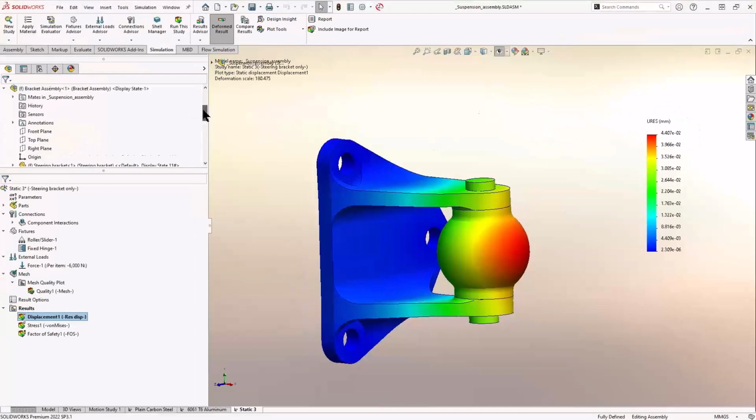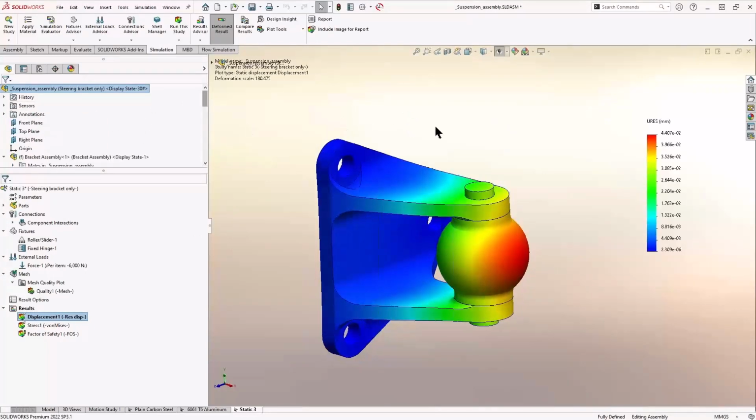Well, that survives the deflection goal, and I can tell because my sensors are not red or yellow. I didn't get any check warning lights there, so I knew that that survived. And we know that the cast one does survive. Displacement is the number one thing this software outputs. So if you don't mess with the mesh, if you don't know all the rules of the game, you probably still have decent displacement numbers.